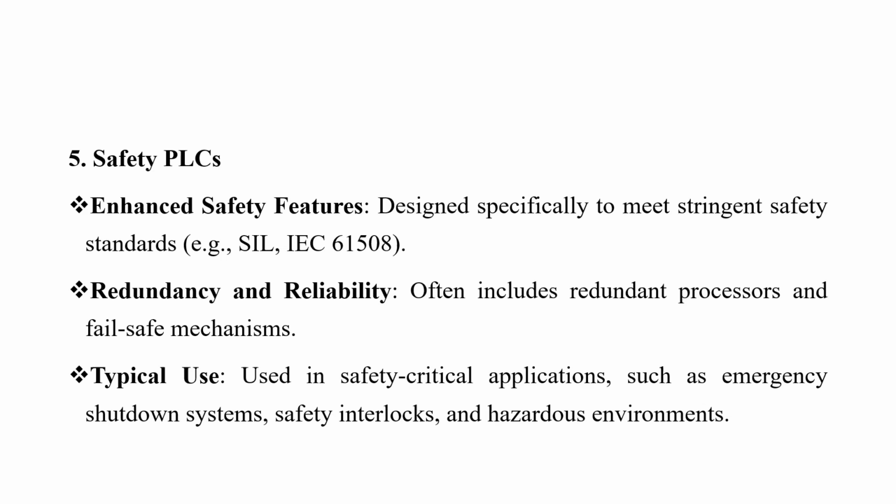Then you have safety PLCs. These are designed specifically to meet stringent safety standards, and IEC 61508 is one of those standards that talk about safety, and therefore you can use these safety PLCs for this.